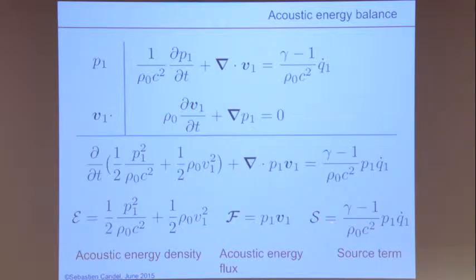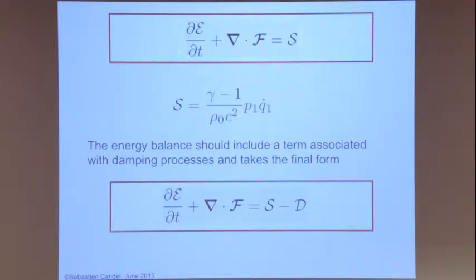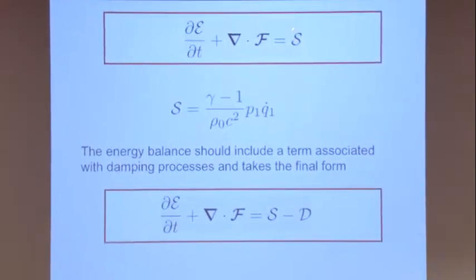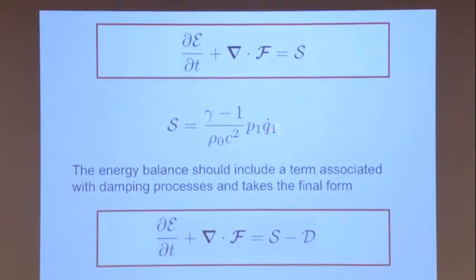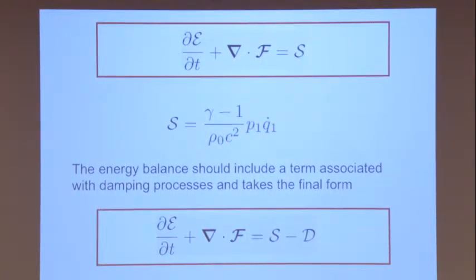You see, this will be positive if the pressure and the heat release rate are in phase, and then we expect that this acoustic energy can increase if this term is positive. So the discussion is about the source term here. This source term, if it's positive, feeds energy into this balance. So we can write an expression of this kind, where S is the source term. The source term is given by that expression here.